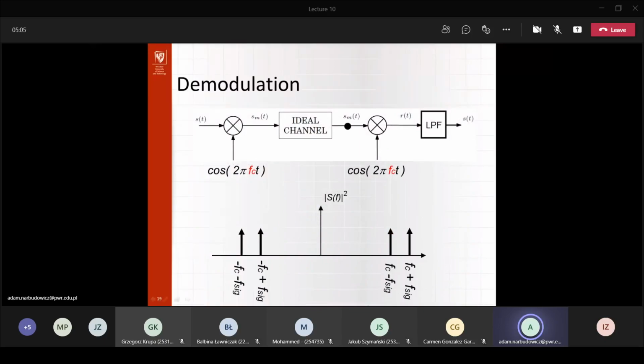So we have our two signals that arrive at the receiver, and once again we multiply them by the carrier frequency, and pretty much the same principle as we discussed earlier applies, right? So we will get the new frequencies, which will be the sum and the difference of all the possible combinations of whatever we get at the input of our mixer. So at the end of the day, we will have 6 different components. So FC, double the FC plus minus F signal, those are those two.